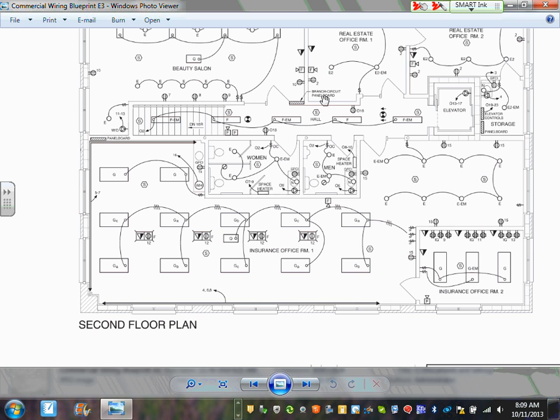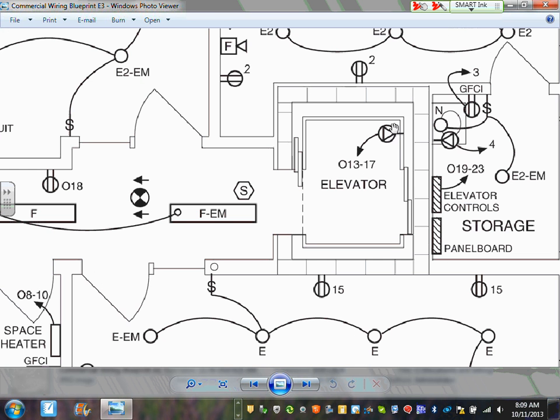What about the elevator? Yes, certain elevators. It depends upon the building code. I believe a 3-story or 4-story building requires you to put one elevator on emergency. You have to have a generator on it. I can't remember if it's less than 3 or 4. We're 3 at Dunwoody, and we require 1. So I think 3 or more are required to put one elevator, not all of them, at least 1, on an emergency generator. So if less than 3, then you don't have to.